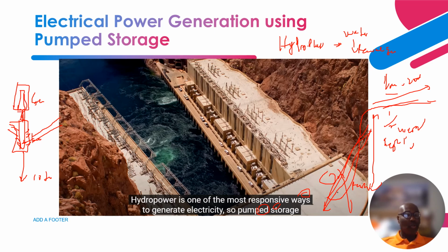So the rotor of the generator starts turning and gradually starts building voltage at the terminal, based on the excitation system of the generator, building a magnetic field around the rotor to induce voltage into the stator that builds the required voltage at the terminal, usually about 13.8 kV.